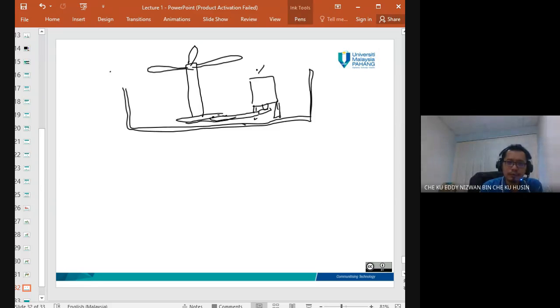So this is the motor, this is the fan, and it has a high vibration in this direction, which is dominated by horizontal motion. And then there is a vibration issue, which is a crack here, a crack on this motor support. So this is a crack issue, and it is due to the high vibration.